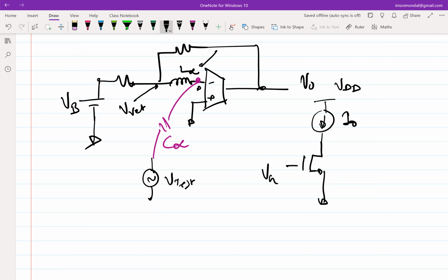Mathematically, the gate voltage will be there, but in practice, because reverse transmission is not possible. So why do you say mathematically the gate voltage will be there? If I put the VG in the ideal equations, which equation will you put? Why? What makes you put that saturation region equation? Because the current source is present. So, yeah, the current source is present. To satisfy that current, VG somehow should be set. Why? There is no connection between output and VG, right? So how will it get set?